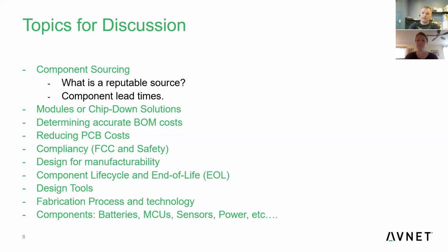The lab that is doing the testing for you is able to pull up the profile for that particular module, because it was actually tested by FCC. They're able to pull up that profile, and all they do with your product is check and make sure that the spectrum that's coming out of your product aligns with that module. Which makes it significantly easier.